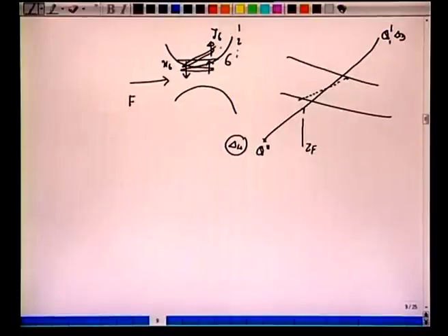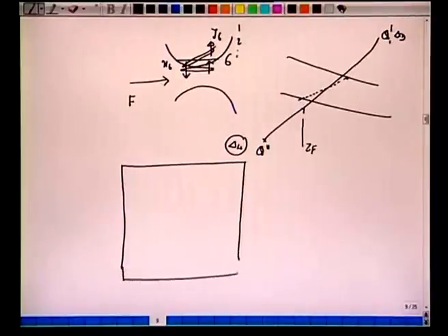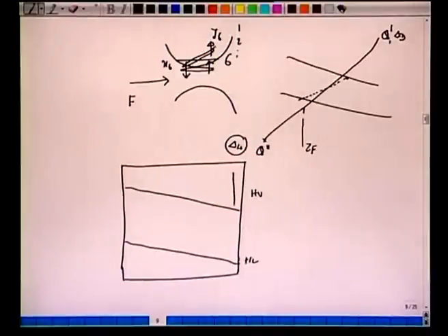All right. So if we continue with the same HXY diagram, now we have to switch. We have to step down to this stripping section. So qualitatively, if we draw again HV, and we have HL, we mark this point. We have this Q dash, and we have this Q double dash. We completed 6 stages here. The last one we are drawing a tie line. Now it has intersected. So that's the feed location.